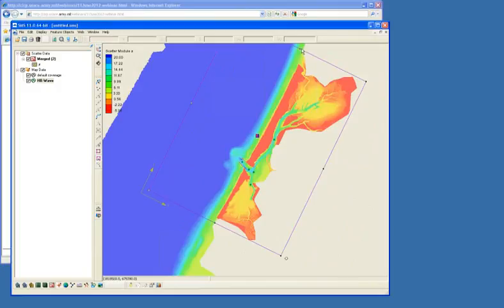And we probably don't even need to represent this entire grid in our grid frame, mainly because the waves will not propagate up into this bay very far, I would think. But we can always try it first and see how many cells it creates, and then if it's taking a long time and we saw from a first approach that the waves weren't getting any farther than, say, here, we could cut some of this information off. We're mainly interested in the interaction with the flow on the open face and through the inlet as it's going through these channels.